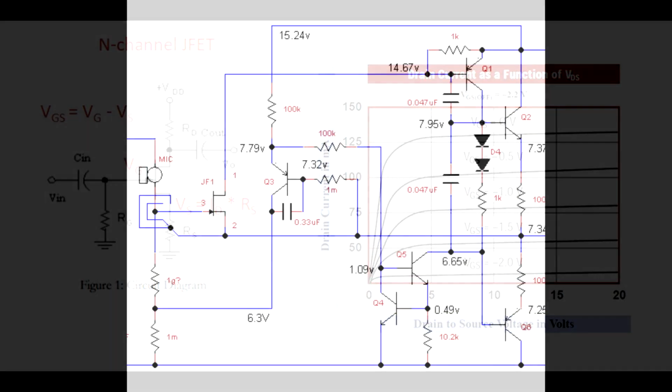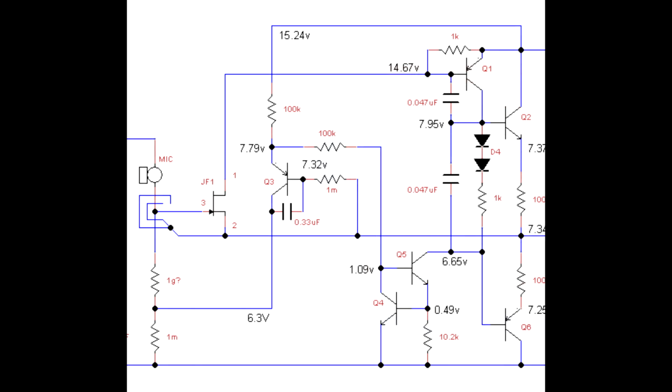So remember that bootstrap circuit. It also is doing a different job, which is providing the bias for the JFET. So the output is going to be about midway between 15 volts and ground. And so the output's going to be around 7.5 volts. And that goes over to the source of the JFET, which means if we want the gate to be negatively biased by 1 volt, then instead of 7.5 volts, we want 6.5 volts on the gate.